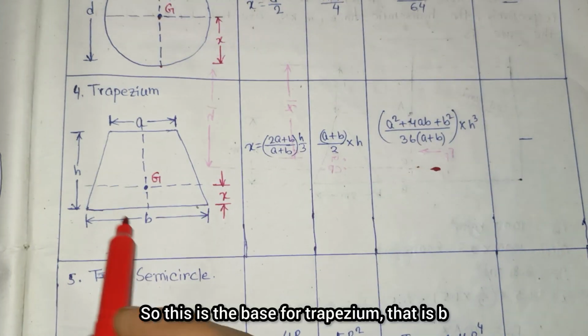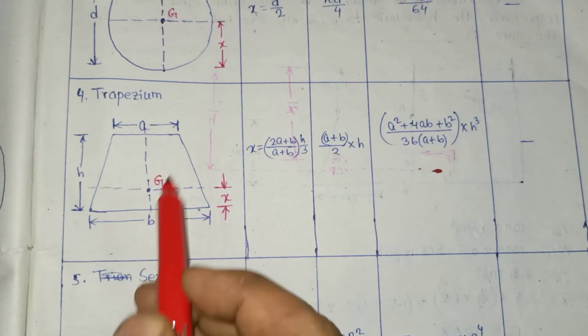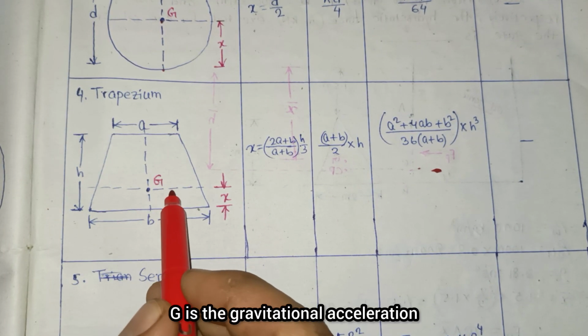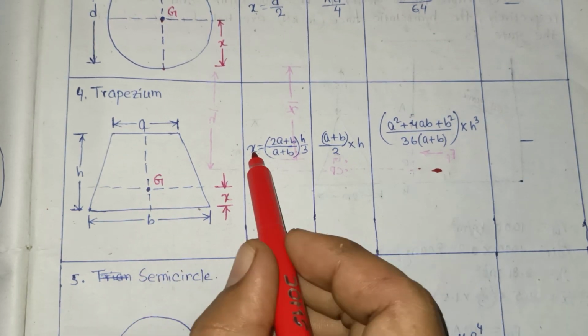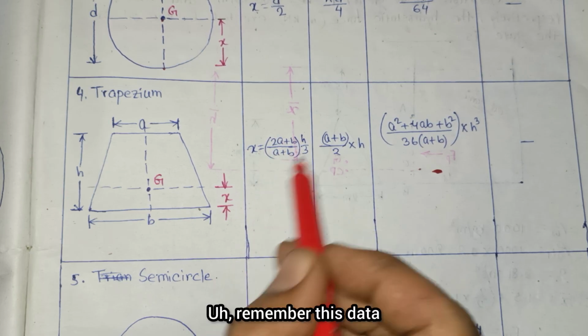For a trapezium, this is the base, that is b, and here the top side is a, and the height between the two parallel lines is h, and this is the center of gravity. The distance from the base to the center of gravity, x, is equal to (2a plus b) by (a plus b) into h by 3. So remember this data.